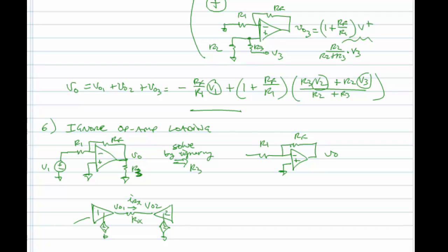But you could solve these independently. You wouldn't need to look at both op-amps together. All right, the last one is consider Thevenizing the source or sources driving either op-amp input.